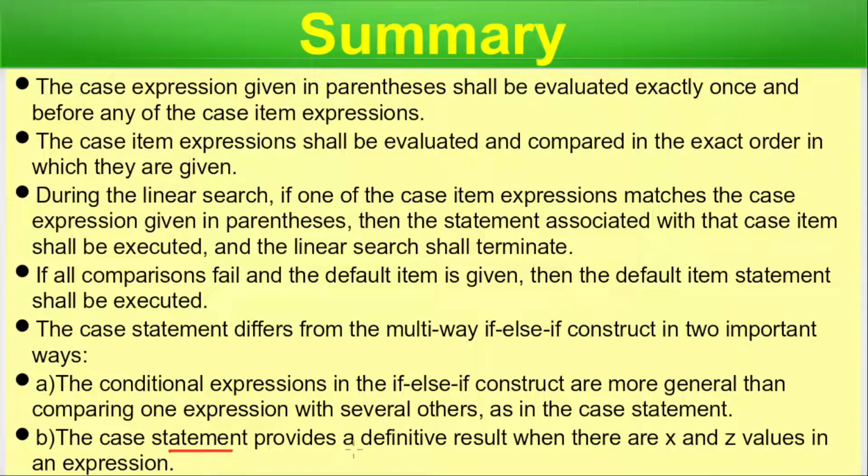The case statement provides definitive results when there are x and z values in the expression. So this is another striking difference, because we can detect the x and z. Also, we have the case x and case z, which we do not have in the if-else-if construct. This is very important from the digital design perspective. You can be asked in the interview: give the difference of if-else-if construct versus the case. Once they ask, you can mention the case x and case z, because they are specific to Verilog. You can answer this. We are done here with the summary slide, and let's move on to the next slide.